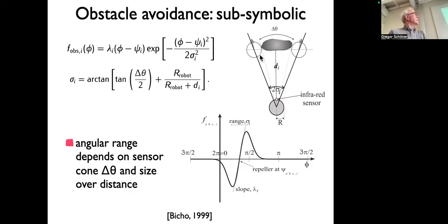But then there's a subtlety in that you would want to avoid the maximal object that could give rise to that sensory signal, which would be one that spans the entire delta phi, the entire sensor range. So to avoid it, you would have to make sure that when your vehicle is right there, it fits. And fits would mean that half the vehicle width, we model the vehicle as a circle, half on the left and half on the right would be appended.